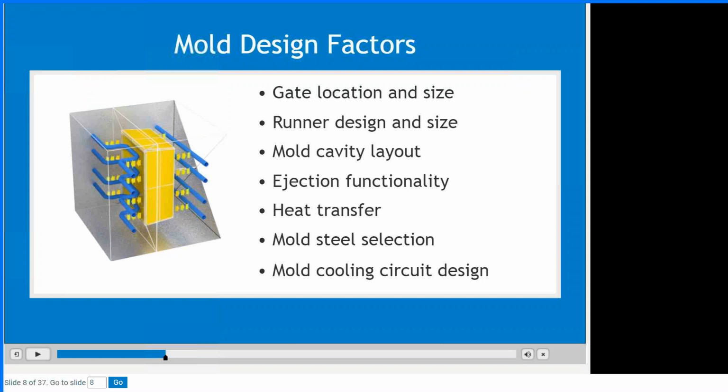If some components in the mold are not touching each other very well or have gaps in between, well, there is no heat transfer. So the temperature is affected. The mold steel itself, be it beryllium copper, stainless steel, or H13, all have different thermal conductivities and therefore influence the overall heat balance in the tool. Yeah, of course, cooling circuits, as you know, are the most important ones.